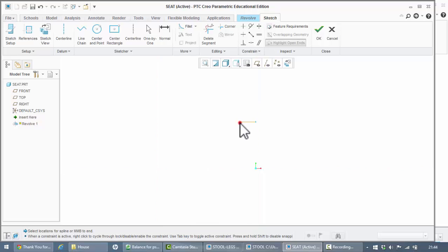I'm going to snap to that point and start drawing, and it looks like I've just got a line drawing tool, but if I put a slight lift up here, another slight lift, and then start curving it down, you can see how the program is interpolating the points with a curve. And I'm going to stop that, bring that around a little, and then again pressing the wheel at that point to stop the creation process.